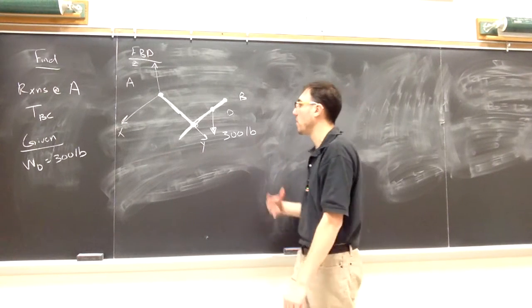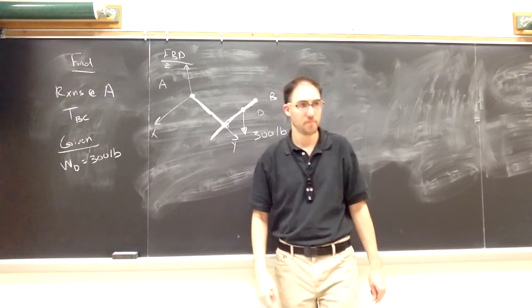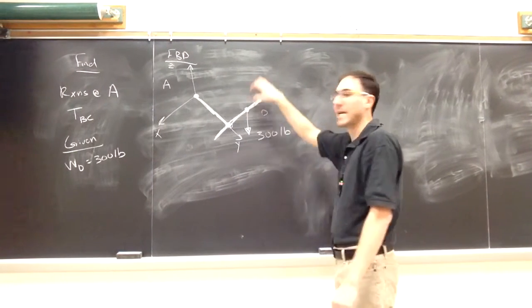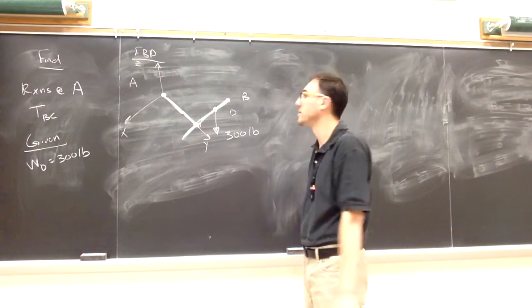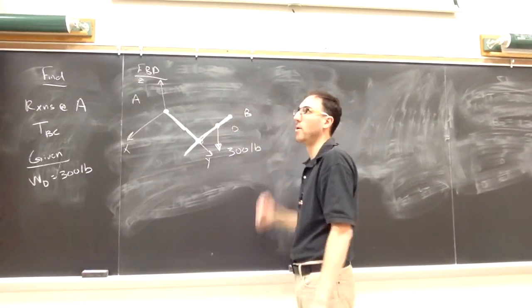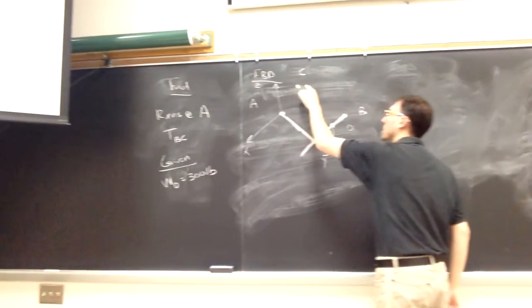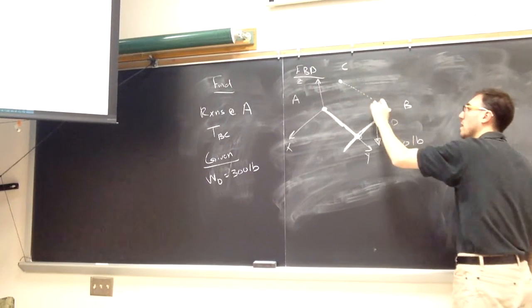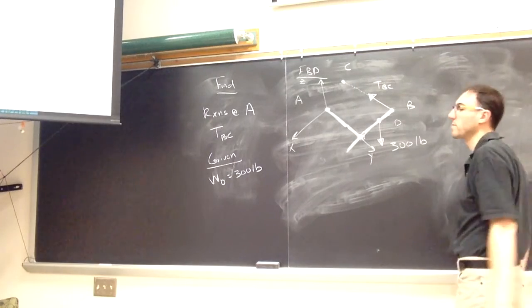What other forces or couples are going to act on the object that we kept? Right, at point B, since I did not include the rope, I'm including what the rope does to my object. Well, it can only pull, and it pulls at B, and it heads towards point C. And I don't know its value, but it's something that I'm looking for, TBC.